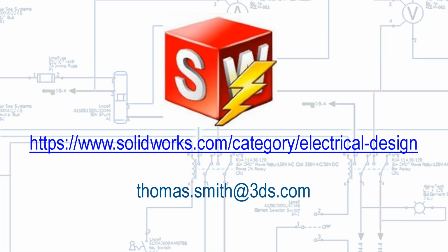They ask, can you also import AutoCAD Electrical blocks and components that have been created? The answer is yes. We have an import wizard that allows us to select a folder or individual blocks that were created in another CAD tool. It then allows us to map those attributes into the SolidWorks Electrical attributes, and that symbol is imported ready to go. Depending on how it was created, there might be some cleanup, but there are some great tools. We can import your title blocks, your symbols, your footprints, your manufacturer's part numbers. So yes, all around.